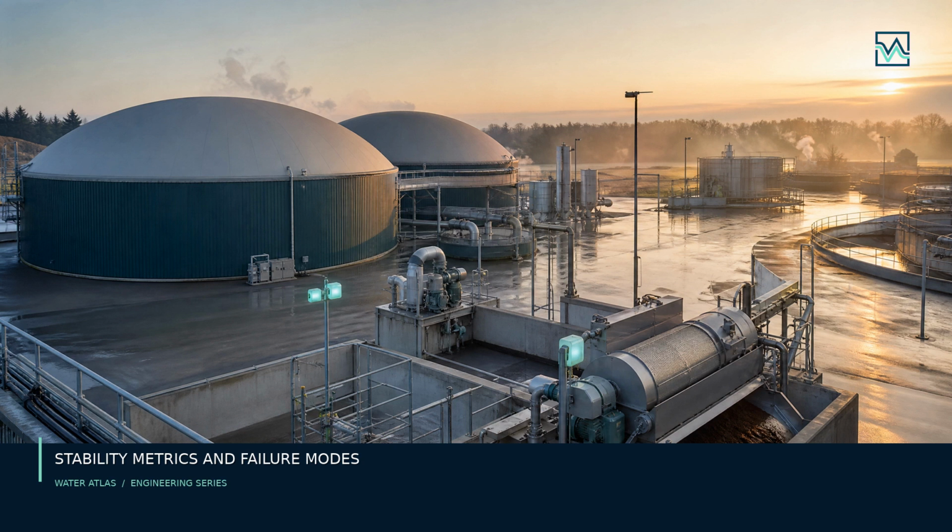Rather than letting struvite precipitate uncontrollably, modern facilities harness dedicated crystallization reactors for controlled resource recovery. By dosing magnesium salts and adjusting pH within a fluidized bed reactor, dissolved phosphorus and ammonia are precipitated into high-purity struvite pellets. Struvite serves as an exceptional slow-release, premium agricultural fertilizer, turning a recurring maintenance headache into a sustainable revenue stream and helping close the global phosphorus loop.